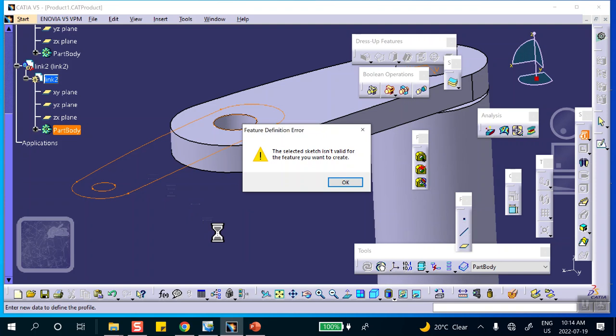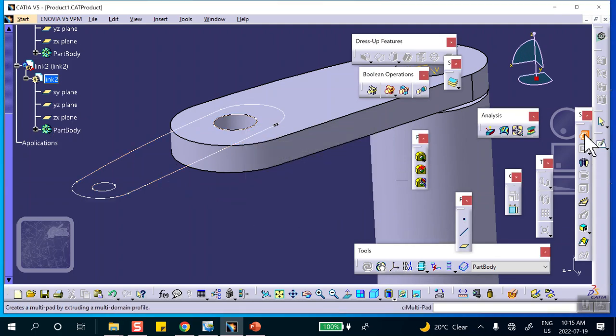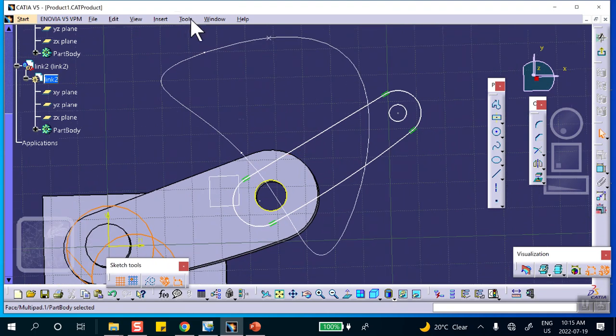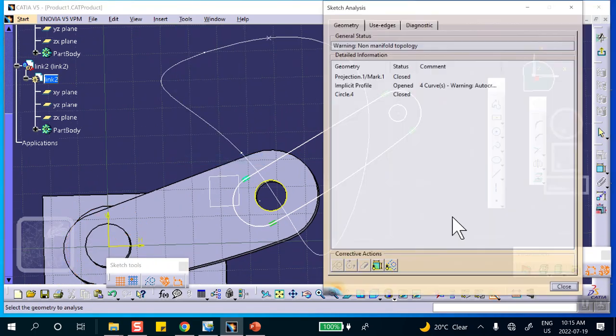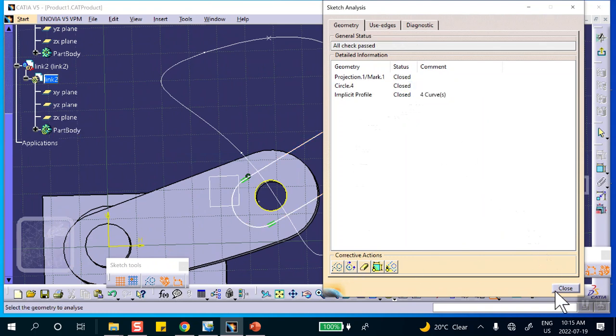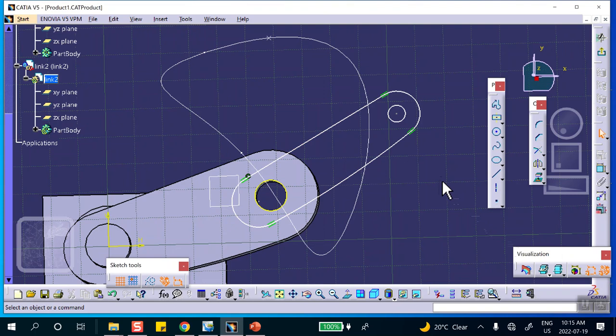Well, first of all, if you don't know, go delete that sketch and do it over. My suspicion is that this is not a closed path. So let's go back in it. Remember that last piece? Let's get rid of this. Let's go back to that path. And there is something called sketch analysis, sketch tools, sketch analysis, open. Okay, so let's delete this, or close it, okay, or delete it. Do it again. I don't care.